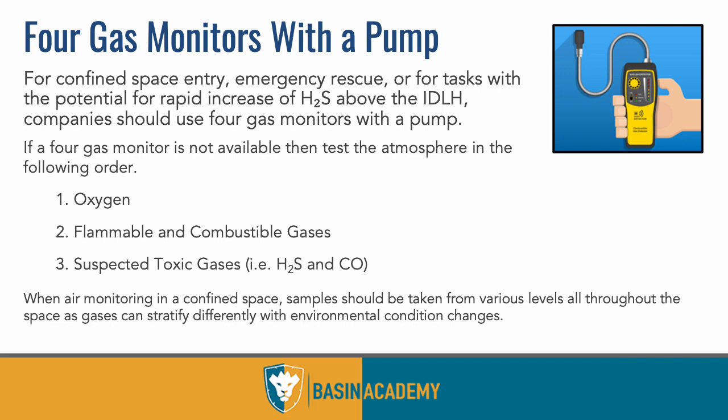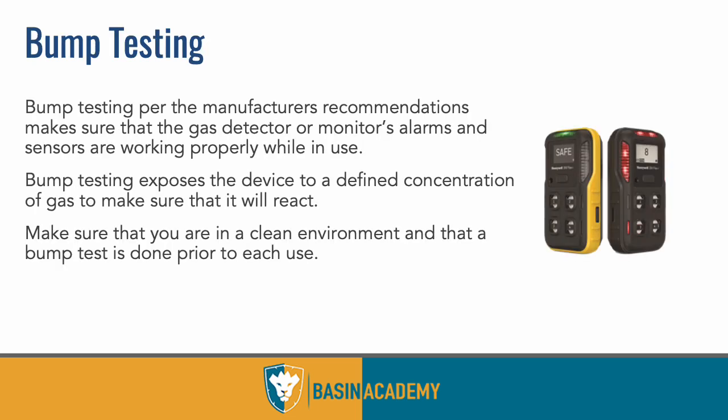So the pump is designed, you put it out there, you wait a few seconds from wherever you're reading, and it's going to bring you back a reading of where your measurement device is and what the levels of concentrations of, again, H₂S, SO2, CO, whatever gases it is you're measuring, that's their designed purpose. So again, they need to be bump tested every day.